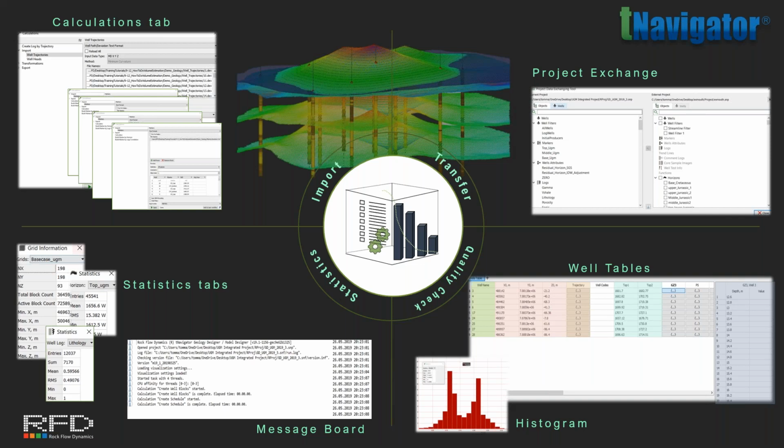Within our wells table tab, we can QC our imported data, and the ellipsis tool that you can see highlighted there allows you to expand the table and look at your well data, whether it be well trajectories, well markers, logs, or otherwise. You can do things like take out any duplicates of data you might have, any errors that become quite obvious. You can take these out as part of your initial QC of your model before you start going to your initial model building.